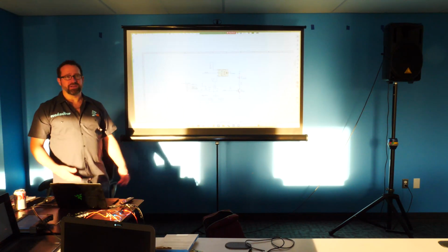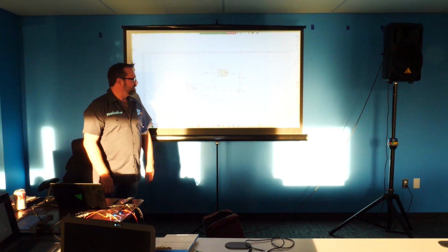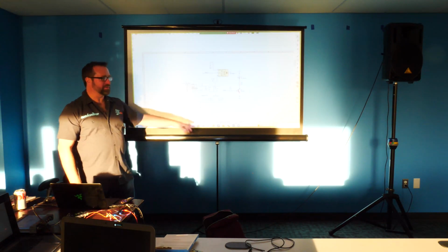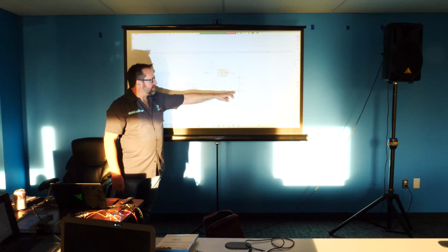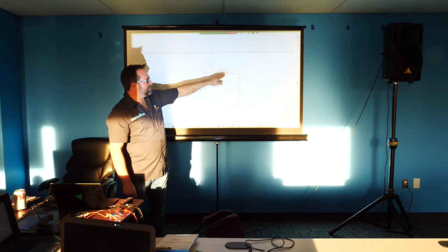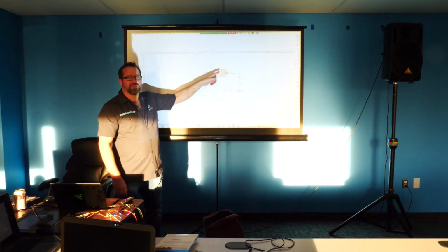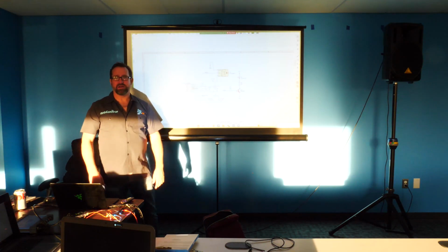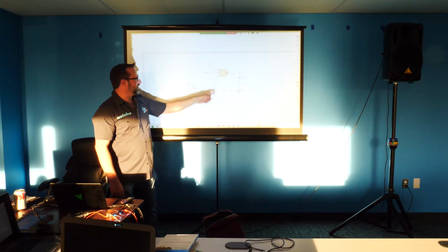That's how radio works: you have an oscillator and then you do something to it, vary the frequency or amplitude. So anyway, that's kind of complicated, but this thing makes it real easy. It decodes that 38 kilohertz and just puts out the actual IR data. So it's a nice clean signal.